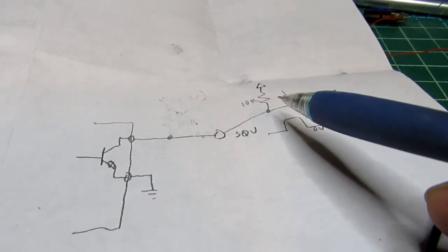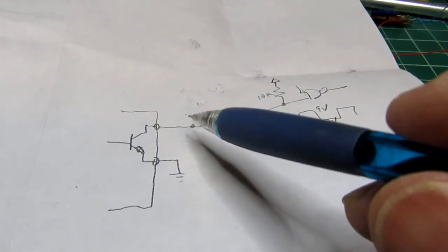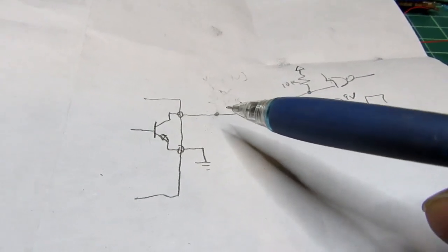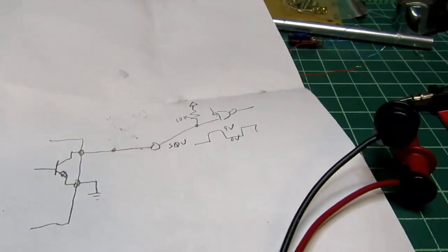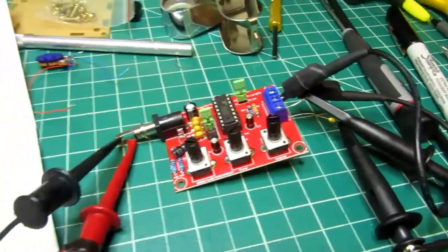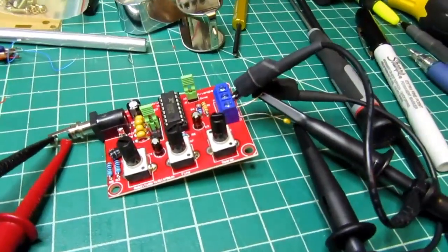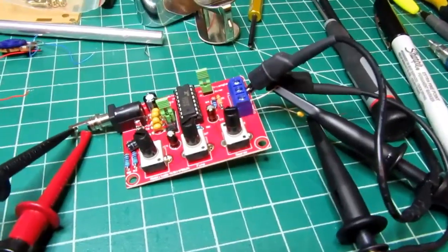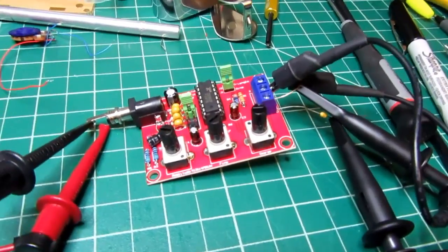Now the pull-up is controlled by the logic power supply circuit, not by whatever you're choosing to power the function generator from. I think that's really the best way to do this, but since I don't plan to use this for its square wave output, I'm going to leave that 10K resistor in here for the time being. I have an idea how I might use this for a particular application. In that case, it doesn't matter what the voltage of the square wave is.